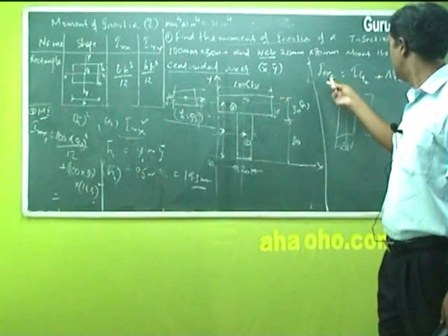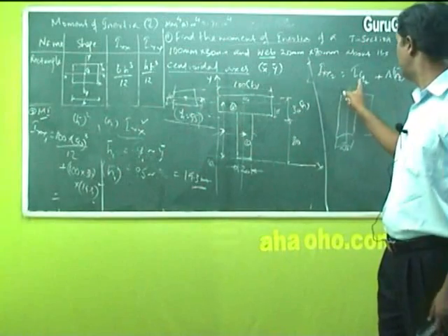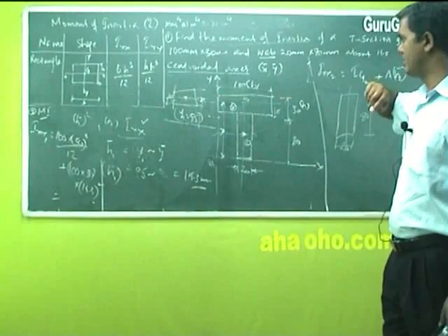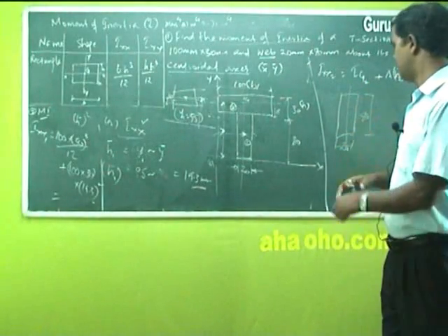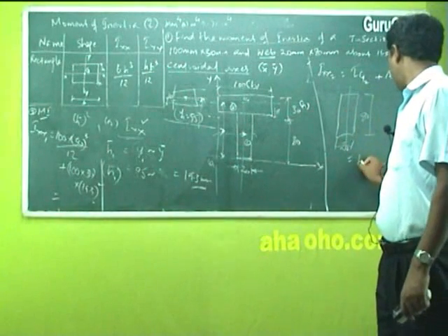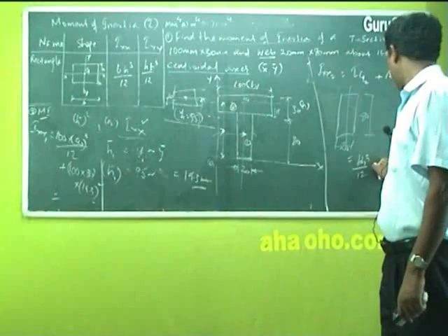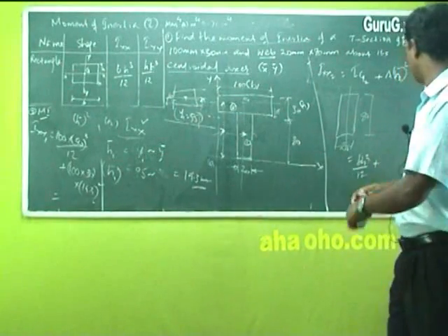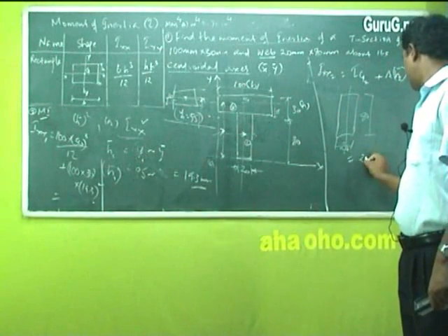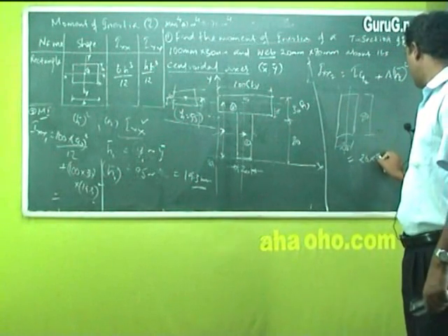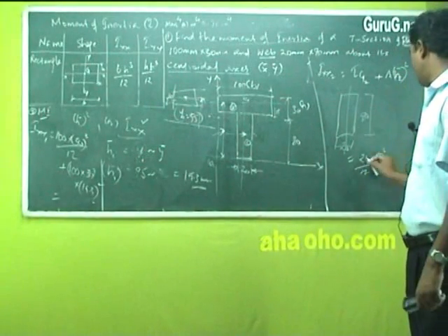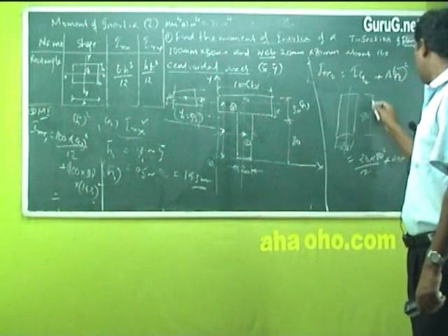That's it. So this is IXX2, again the formula. What is IY given here? This is IXX2. Oh, I am doing IXX for 2. Again BH cube by 12 plus. Okay, instead of writing the formula, I'll write the values. What is breadth here? Breadth is 20. Height is 80. Cube by 12 plus area is L into B. L is 20 into B is 80.